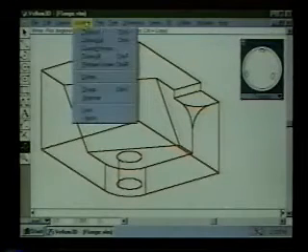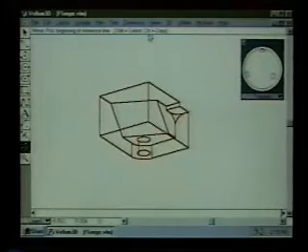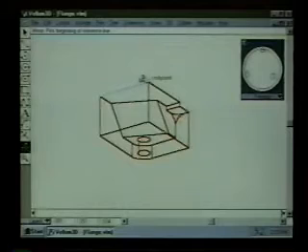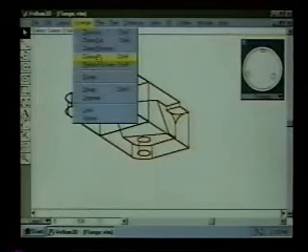Now I'm going to zoom out one time just so we can see this happen here, and give it a mirror line. Now it says in the message line control equals copy, so I hold the control key and I draw a mirror line from here to here, and it flips it right through there. Now we'll say zoom all.